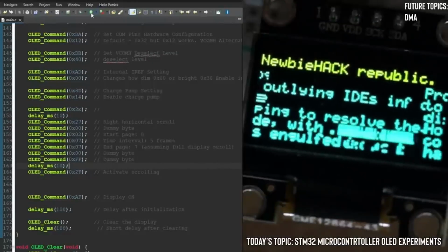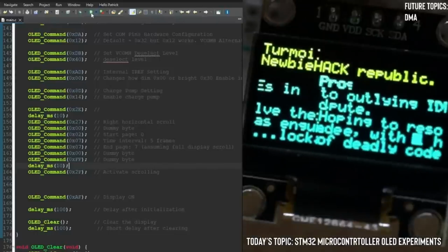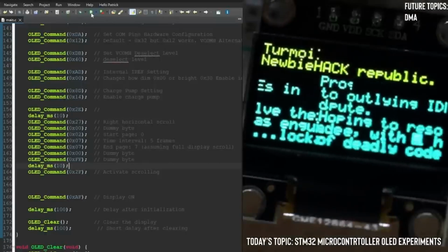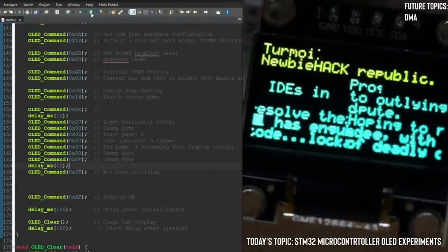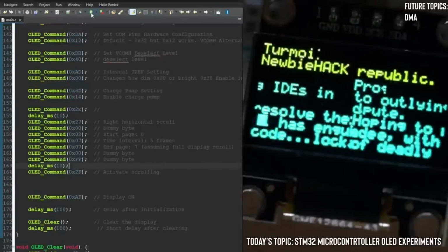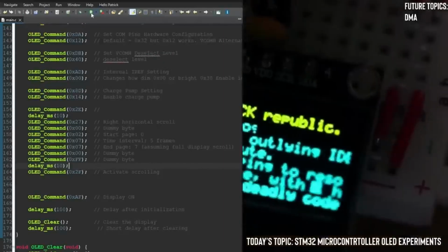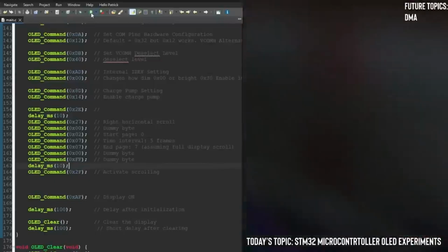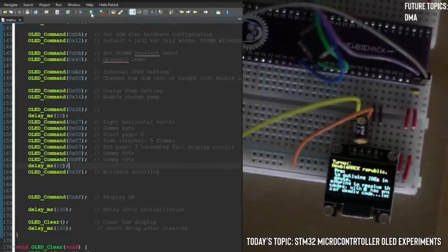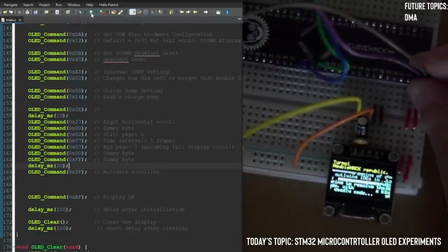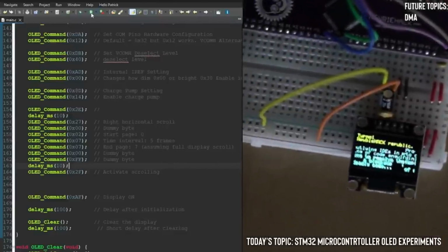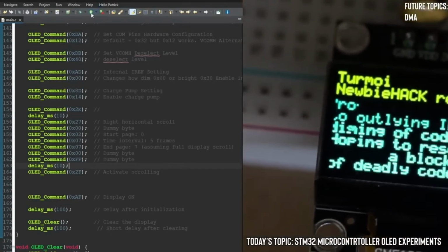Removing the power from both, there shouldn't be any. There's no circuit if I just do one of them. So unless it's getting some power from the SWDIO and SWCLK pins, I don't see why I need to do that, but I can do that for sure. And it still looks like there's. I'm going to go ahead and take both of them out. I'll give a better view of this as I do it. It's a little harder to see what's going on the screen though. Yeah, so doing both and doing one are essentially the same thing. That looks a little bit better, but still there's artifacts. Maybe there's no artifact and that's supposed to be there?